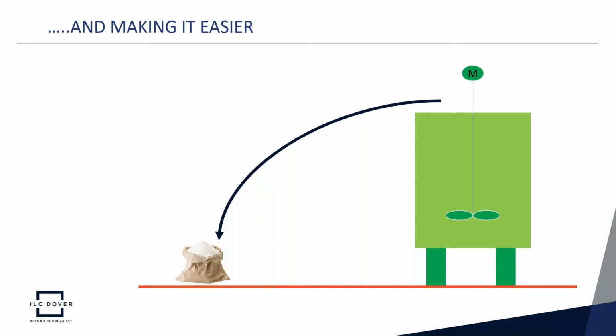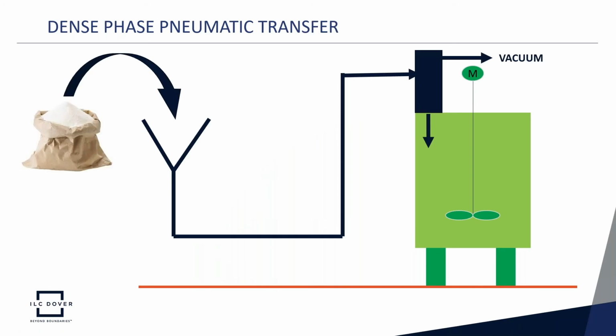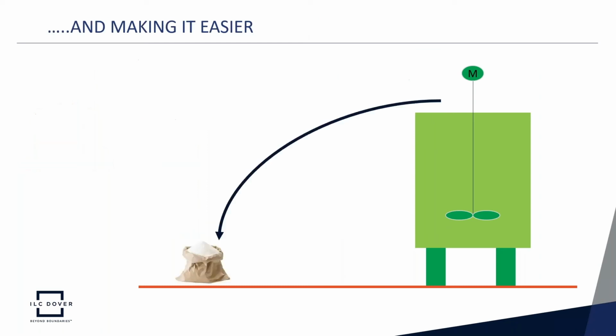So looking at this powder handling operation, it can be made immediately easier by bringing the powder charge point down from the crowded top of the tank and completing it on the floor of the hydration area. This not only eliminates the transportation of the powder bags to the top of the tank, but allows the operation to be undertaken in an open, clear, free area, greatly improving the overall ergonomics. So what technologies can be used to charge the powder from this remote point and get it into the mix tank?